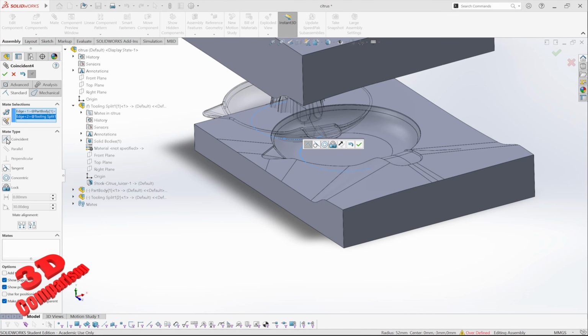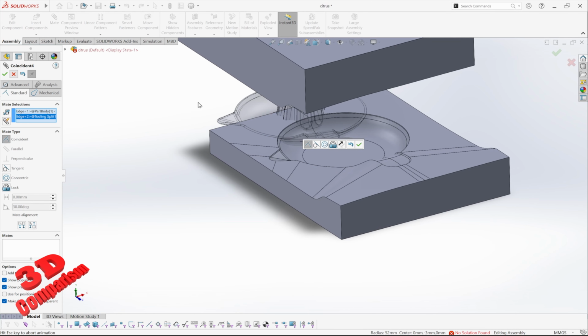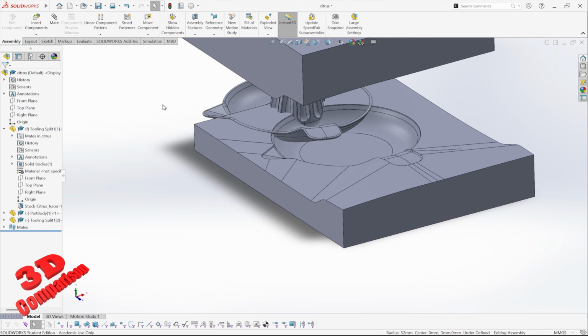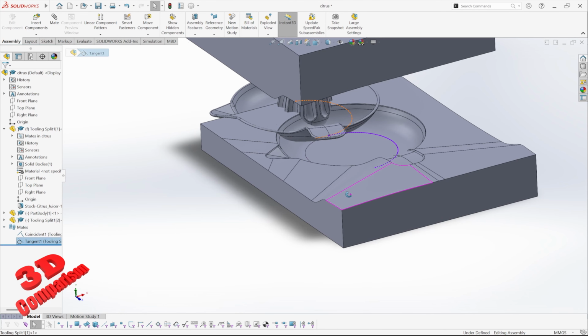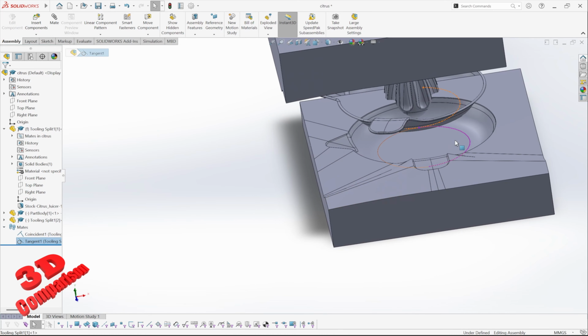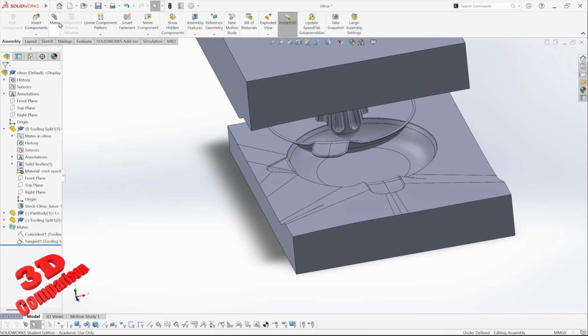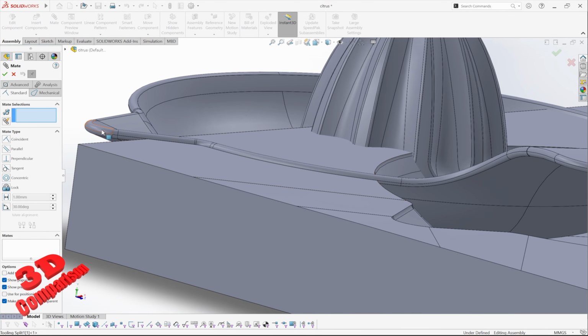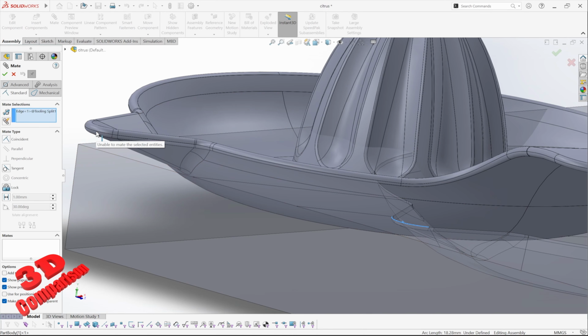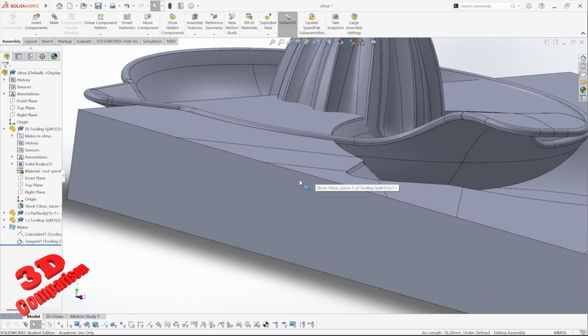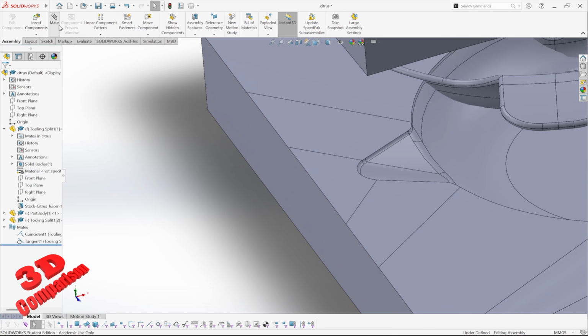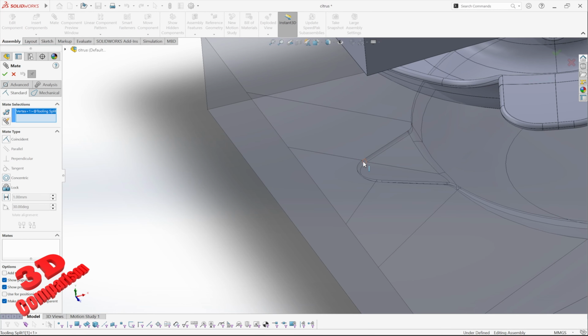So I have the possibility over here to do a concentric, but it doesn't really allow me to do a coincidence between those two. So as you can see, we still have those two mates over here. So I have half of that circle, which was a viable and okay solution in this case, and we have the other one. So we still need an additional constraint to have this locked together. So I'm just gonna try over here and see if those will work. As you can see, those will not work as well. I'm just gonna go with a point selection then.